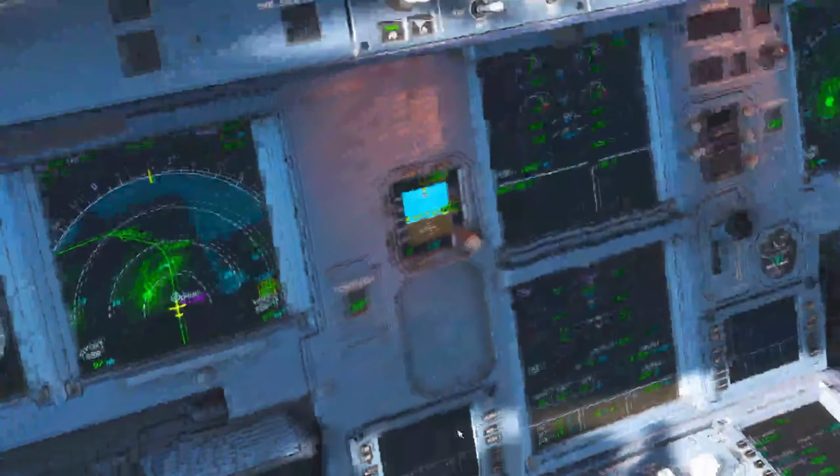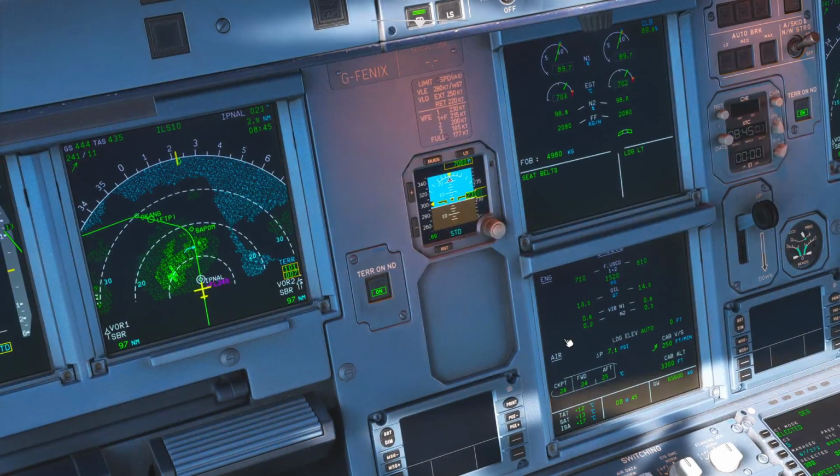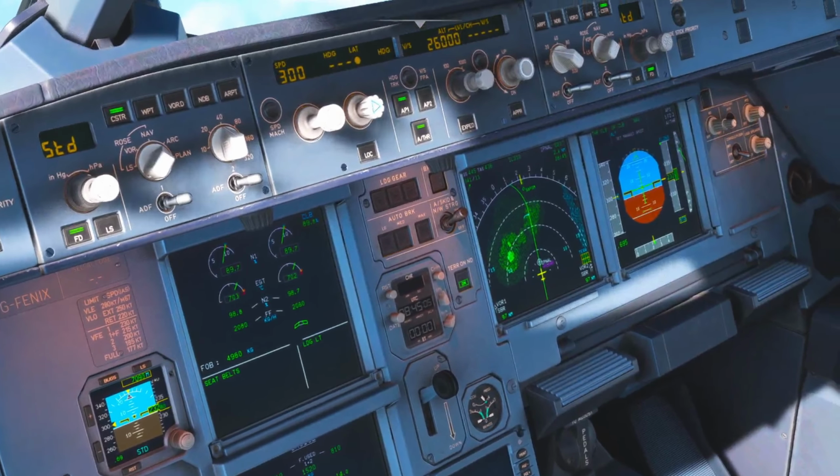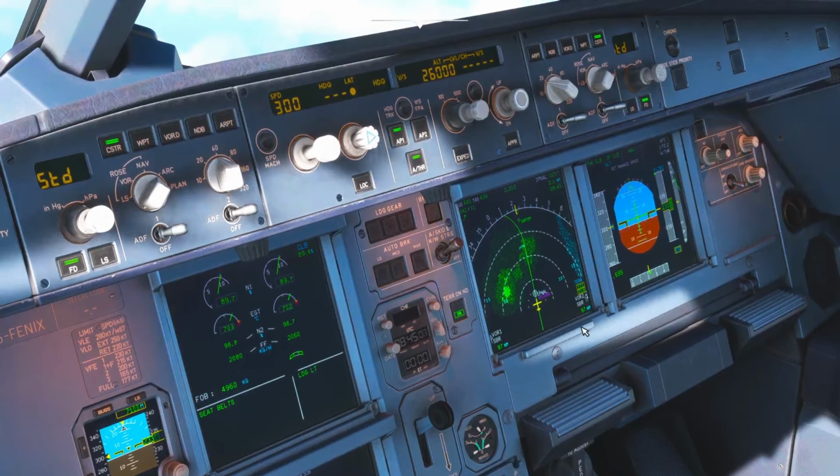What is managed versus selected? The auto flight system, AFS, in Airbus offers a way for pilots to choose between highly automatic modes, automatically managed by the flight management and guidance systems, and modes manually selected by the pilot. There's a selected mode.